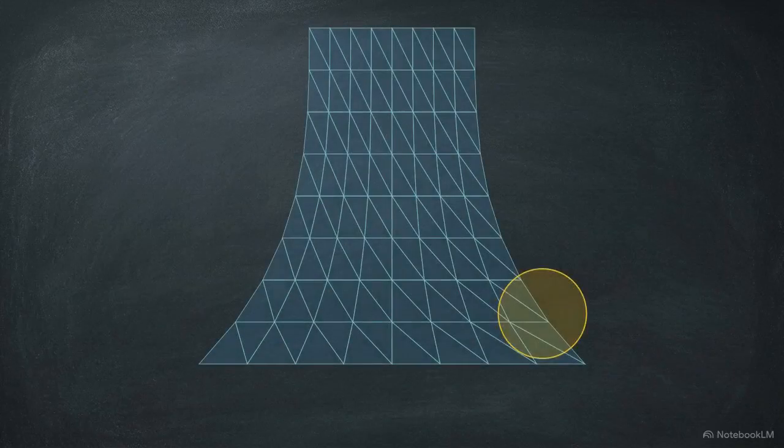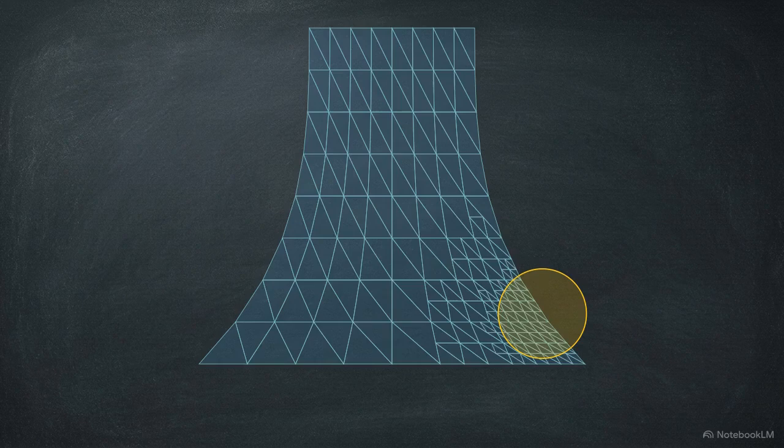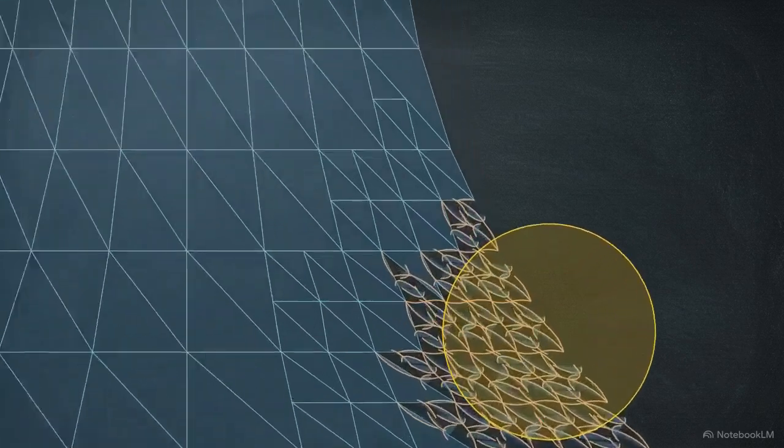Even with stable elements, a fixed global mesh often fails when it encounters severe localized stress. This 2D gear shows localized stress. To solve this, HPQ adaptivity dynamically recalculates the mesh. H adaptivity shrinks physical elements specifically where errors are highest. P adaptivity elevates the mathematical polynomial order, moving from linear to quadratic curves, increasing accuracy without cluttering the entire model.